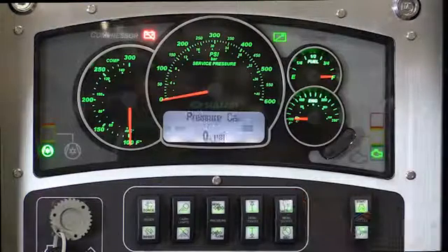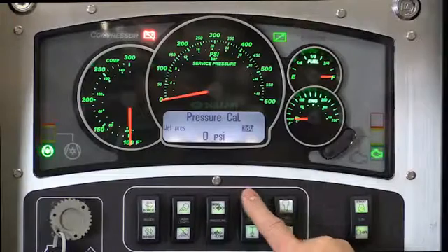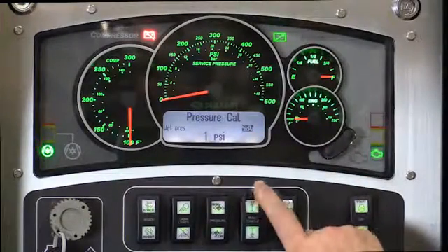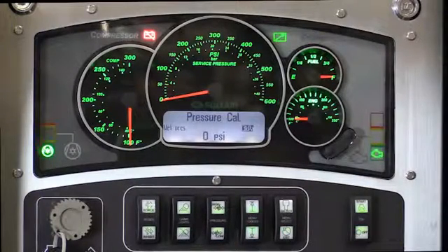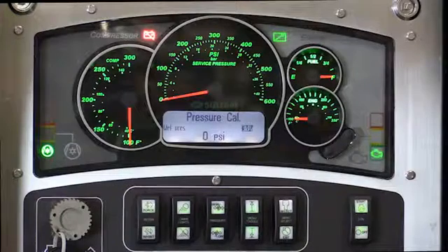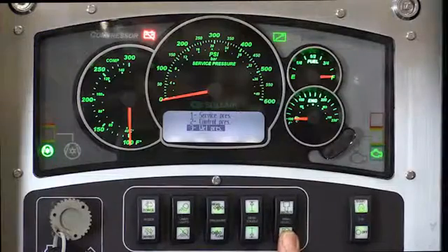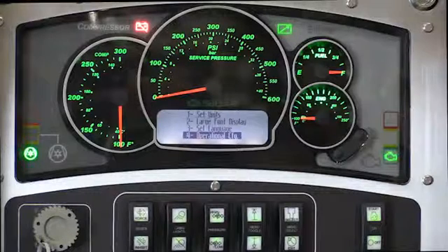Next, select wet pressure, which is P3. Activate your selection by using the select button. Go in and calibrate your transducer. The transducer is calibrated by using the toggle up and down arrows to change your offset and zero that out. The goal is to ultimately read 0 psi in the center. Once you're calibrated, again, use the exit button to exit out of that calibration screen and go back to your submenu.